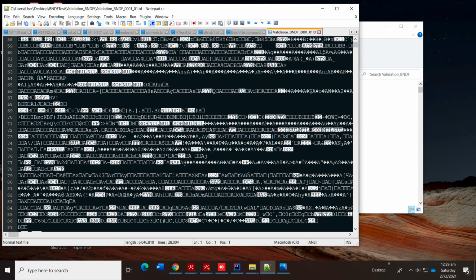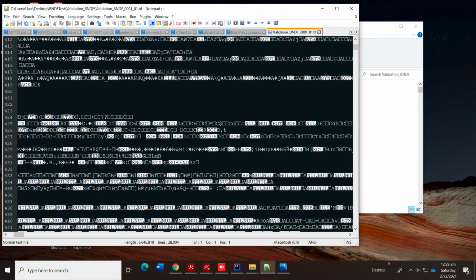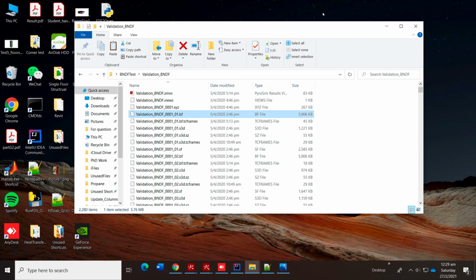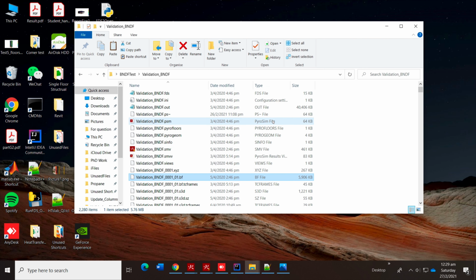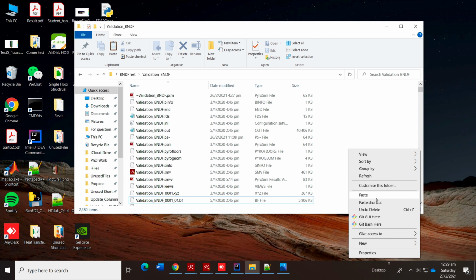This is in binary digits, so you cannot extract temperatures or anything from it. But FDS comes with one software in its package called FDS2ASCII. It can convert the data into readable numbers. Let's see how it does.